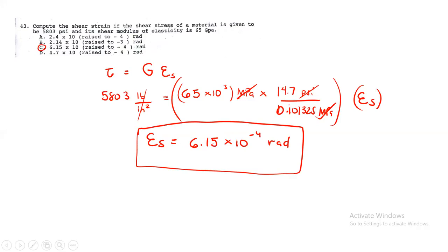The next one, number 44. Which of the following statements is incorrect? The answer here, guys, is letter D, the longest one. Grashof's rule states that the sum of the shortest and longest link cannot be less than... so it should not be "cannot be less than," right? So, that statement is false.